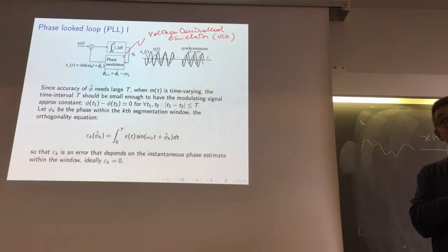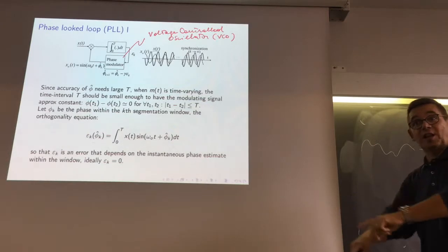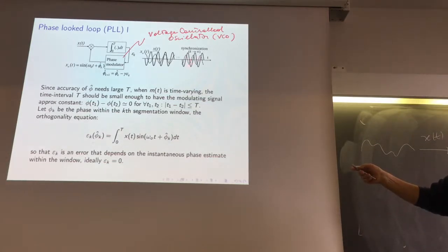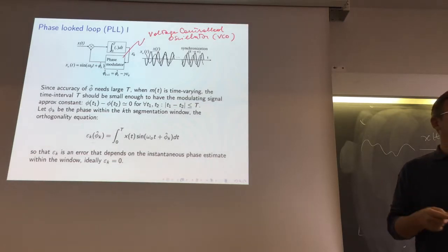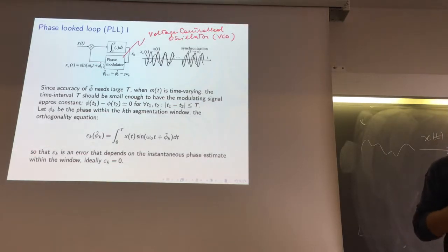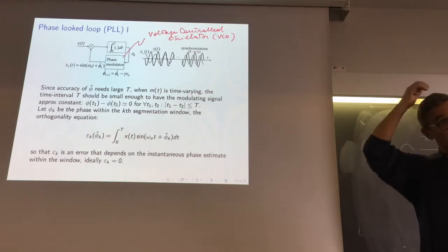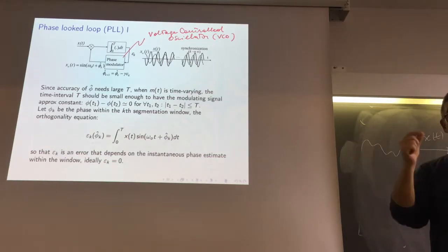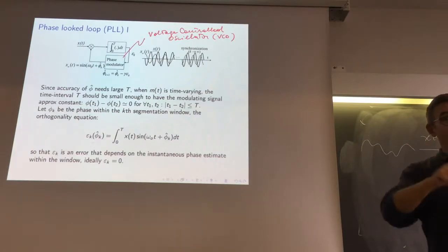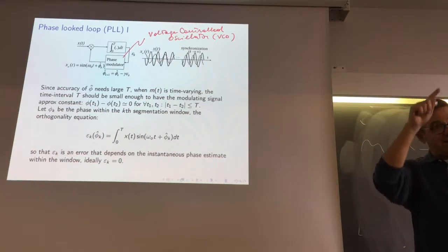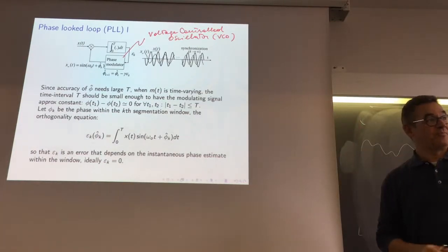So when I'm using a VCO, the two signals are not going in the same way. When one is generating a sine, the other is generating a cosine, and they are in quadrature. So for the electronics, when they say these two signals are synchronous, they don't go the same way. They are in quadrature with one another.